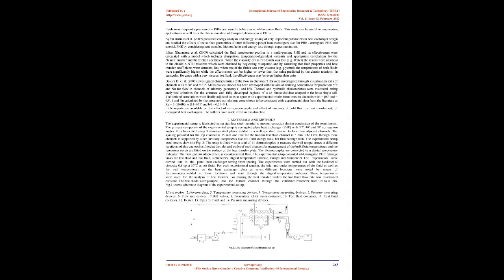conducted the pressure drop experiments for 10°C and 20°C inlet temperatures and developed a two-phase pressure drop model based on the kinetic energy of the flow in order to relate the two-phase pressure drop data to the single-phase data. The model predicts two-phase pressure drop within 15% of experimental measurements.